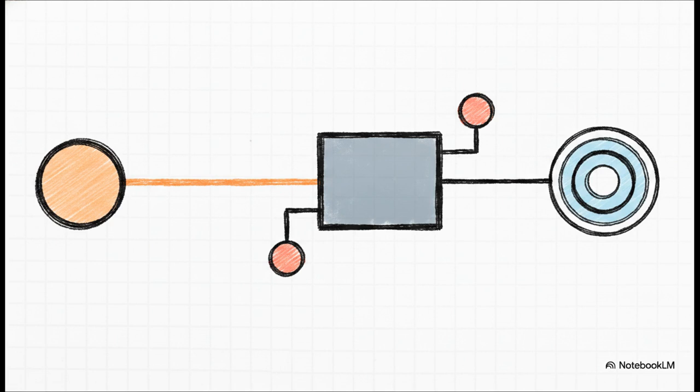Let's look at our intercept variables. IN1 is our start button, which is normally open. CR1 is our primary hold, the motor coil. IN2 and IN3 are our 2 halt sensors out in the field. And crucially, we're introducing AR1, an auxiliary relay. I really want you to specifically note that AR1 is going to act as a normally closed or NC contact, so we can physically intercept and break this circuit.